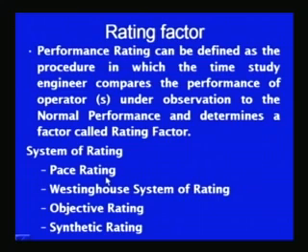Different methods have been developed over a period of time to find out the rating factor for an operator during the time study, and these are known as the pace rating, Westinghouse system of rating, objective rating, and synthetic rating. Pace rating is about the speed at which the worker applies himself for carrying out the particular job, while the Westinghouse system of rating considers the skill of the operator, the pace at which he is working, the kind of conditions in which he is working, and the consistency